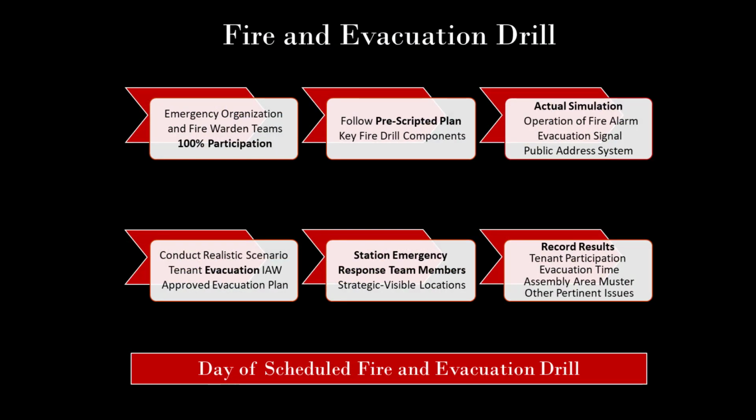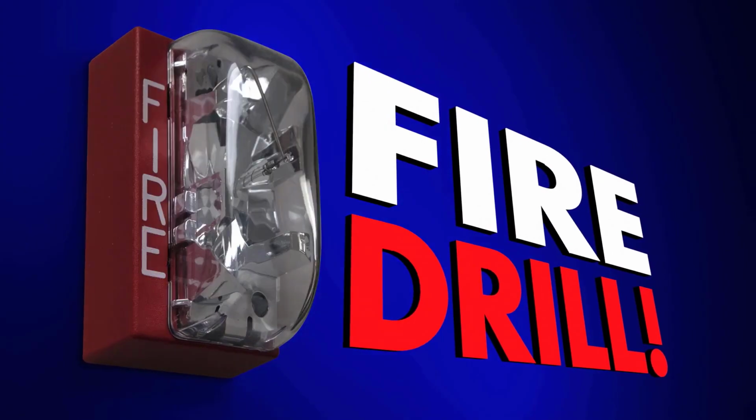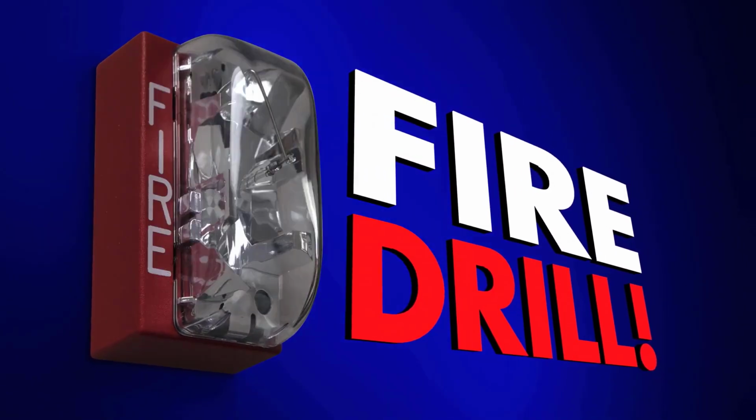To facilitate an organized, efficient fire and evacuation drill, the facilitator should plan specific actions in a fire and evacuation drill timeline. The emergency response team and tenant fire wardens should be strategically positioned so that they can observe and record life safety system and tenant evacuation performance. The fire and evacuation drill must simulate an actual fire alarm condition, including sounding of the building's evacuation signal. The fire department's approved evacuation plan must also be followed during this exercise.